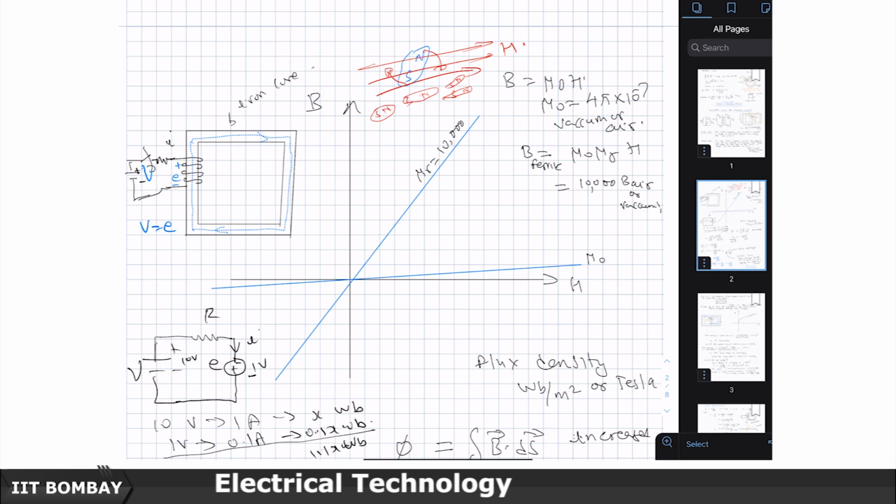And so, if you put so many small magnetic elements parallel to the H which you have applied, then effectively, if this H was creating only B equal to mu 0 H, each one of them is going to add to the B which is being created, and therefore, the B in the ferrite core will become mu 0 mu r H, and this mu r could be a very large number like 10,000 or so.